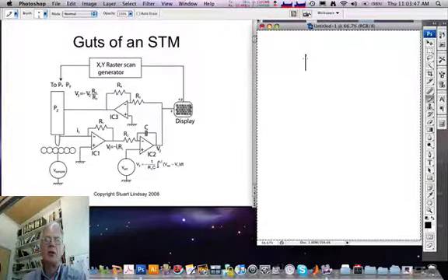So let me introduce you to a marvelous thing called an operational amplifier. These are very high gain chips with field effect transistors at their input, so they take essentially no current, and their gain is almost infinity. That means that even the slightest voltage difference between these two terminals matters. One is a non-inverting terminal, in other words, if this voltage goes up, the output goes up. The other is an inverting terminal, in other words, if this voltage goes up, the output goes down.